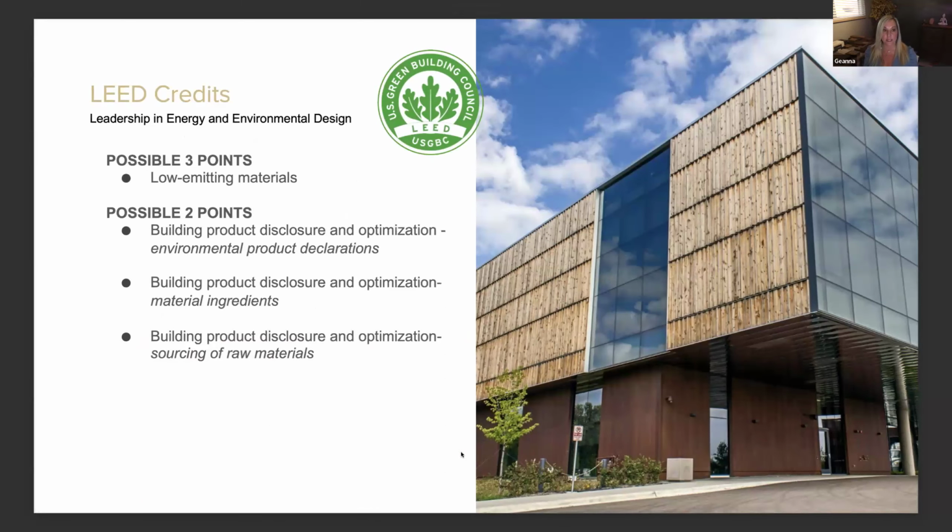There are different LEED points available when you're dealing with a government project where you're trying to go for LEED points. You can get FSC wood for your LEED projects. FSC wood does drive the price up by about 30%. We don't stock FSC on the ground, so it's got to change chain of custody. A lot of the manufacturers have the chain of custody to get you your FSC. It's going to be longer lead times and it's going to be an additional upcharge of about 30%.